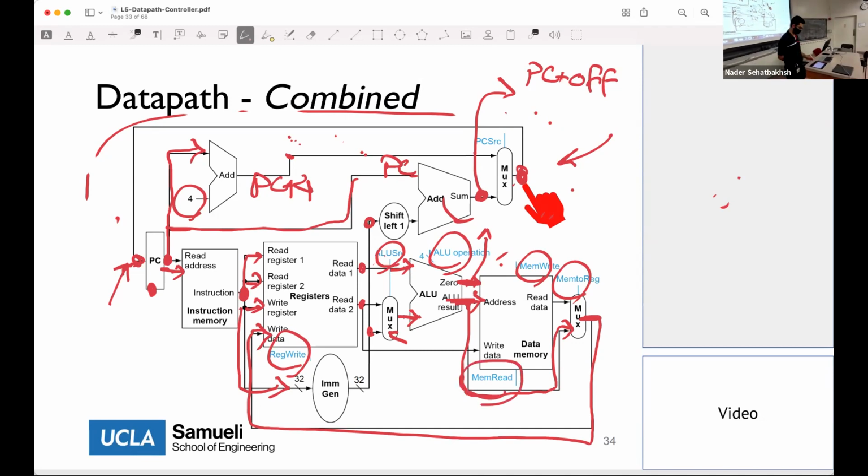This one? That's the data memory. That's the entire data memory that's going to read data or write to it. SW and LW, yes. As I said, in the real world, the instruction memory and this one are the same thing. Since it would be much more difficult to show this together, we're going to divide it like this. But in reality, they are actually the same structure. They're just different addresses, okay? They have a separate port for the instruction and a separate port for data. But again, to make things simpler, we just divide them into two pieces.